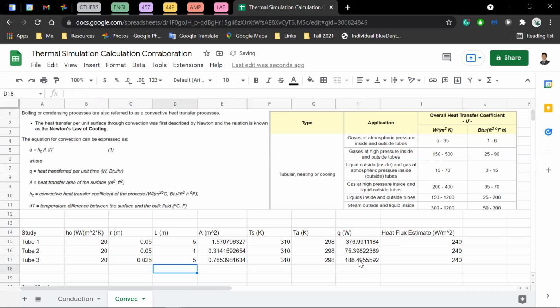Okay, so I changed this value a little bit, but I used the estimate for heat flux as my SolidWorks input. In this case, I did calculations first and then used this as my SolidWorks input. So technically, I'm validating my calculations with SolidWorks as opposed to validating SolidWorks simulation with my calculations. But I think you can do it either way, to be honest; you're corroborating your results either way. So either way should be fine, as long as the results are roughly in the same ballpark.